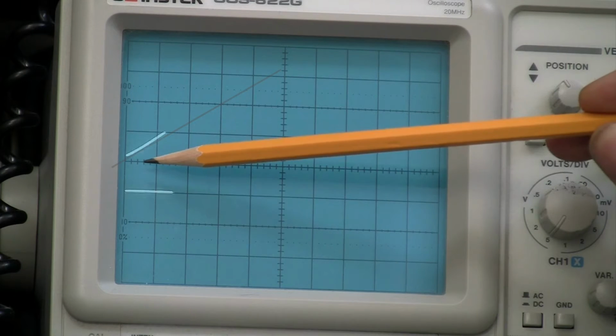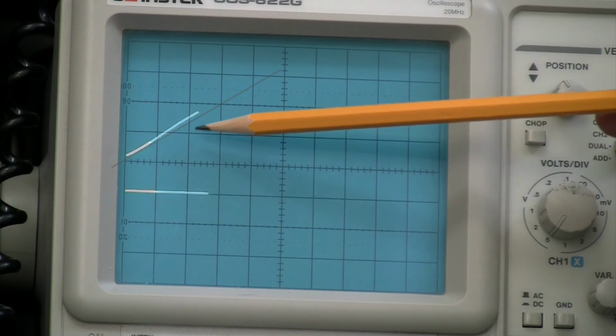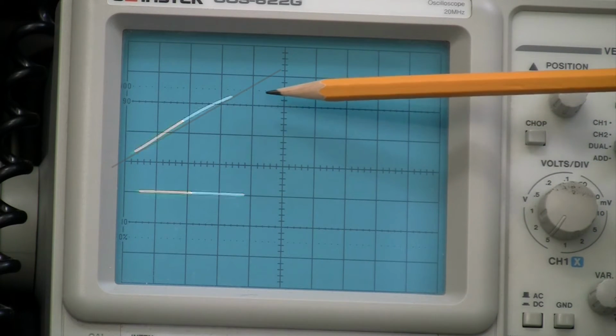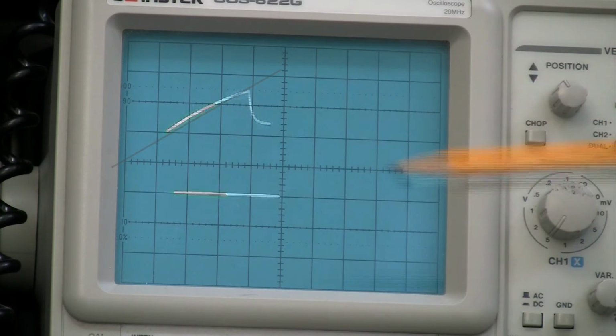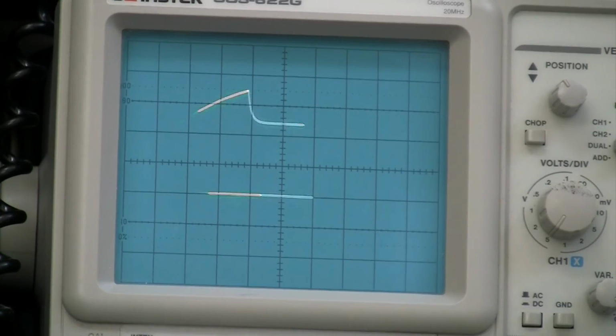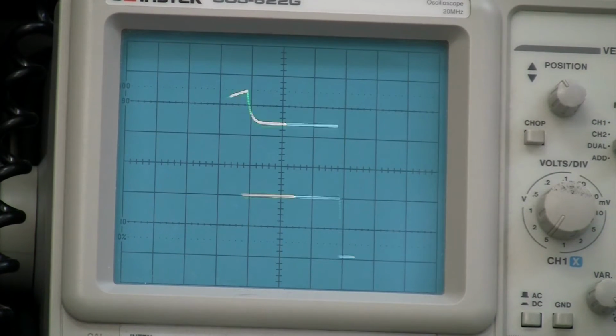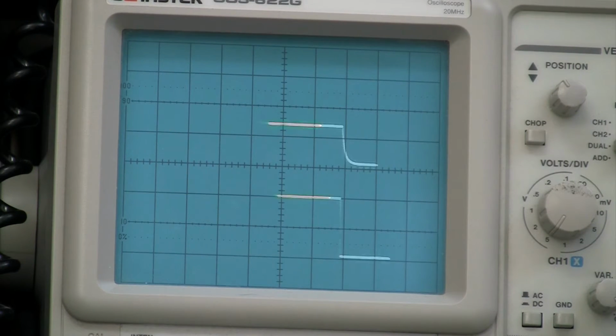It's a little bit concave here, then pretty linear, and maybe slightly convex, and the amplitude is now close to 12 volts. And I've only got the knob turned to about 4.5, so I'll continue turning that up, and then you'll see the next interesting thing, which is that it will start to clip up here at about 13 volts.